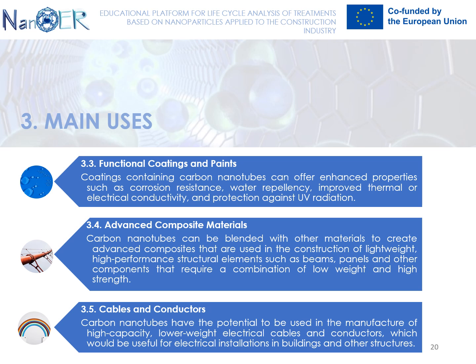They can be dispersed in polymer, metal, or metal oxide matrices and improve the electrical properties of the material. When they are dispersed in a polymer, they improve the mechanical properties, such as the viscoelasticity and the fracture strength of the composite. Nanotube-reinforced composites have been created successfully until now, and they will certainly be investigated for large-scale production in the next decades.